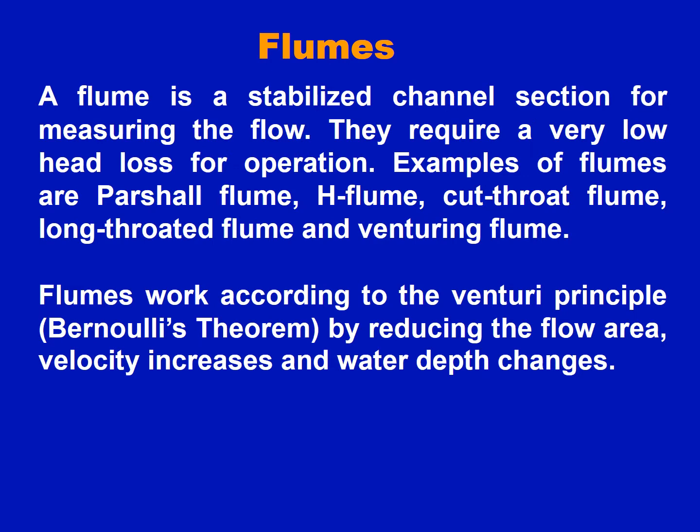So pressure head, that means P, plus velocity head, V square upon 2G, plus potential head, Z. That means for two points in a channel, P1 plus V1 square upon 2G plus Z1 is equal to P2 plus V2 square upon 2G plus Z2. Now suppose at section 1 the size of the section is high, that means the area is high. At section 2 the area is low.